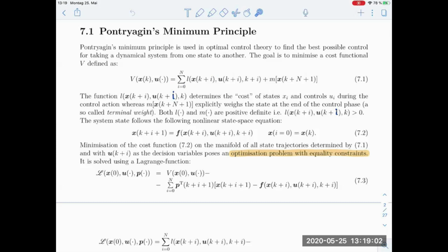Okay. Well, we of course cannot just optimize this function here in u and x of k alone, because we have x at the future times here as well, and they of course depend on the initial state x of k, and usually on all the input values over time, and they depend on that by our model of the system. Our system dynamic model needs to be incorporated into this optimization now, because otherwise it just doesn't describe our system properly.